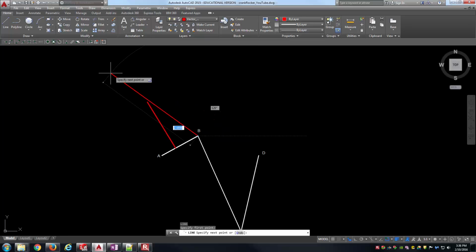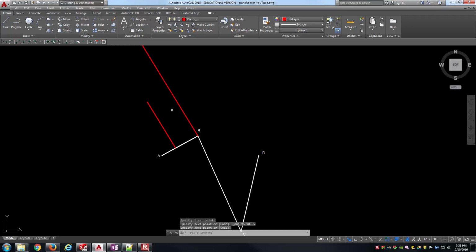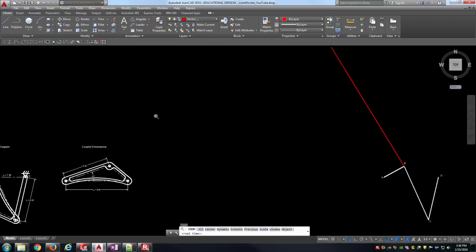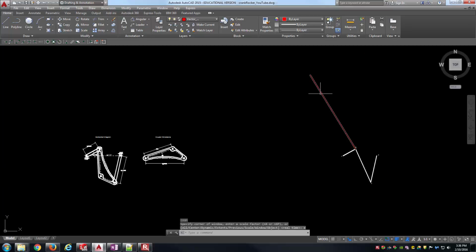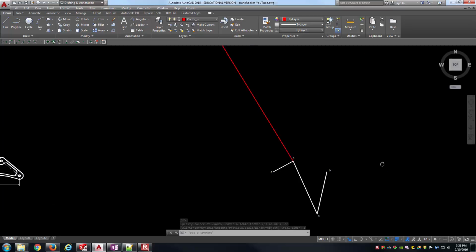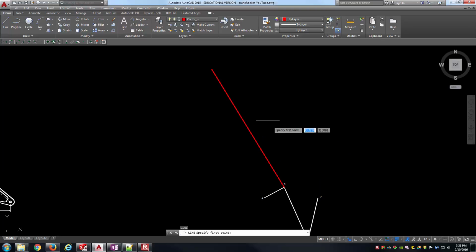and then I'll get a line tool going again. Here I'll use the parallel tool, and so I'll wait till it snaps there. I've got the locator. Now it's going to run a line parallel to that perpendicular line. So this line should be exactly perpendicular to line segment AB there. And so this line is going to represent that vector velocity of B. And so we said that had a magnitude of 18.85. And so entering that into AutoCAD and hitting Z enter allows me to create my first line here. And that red line is the vector VB.